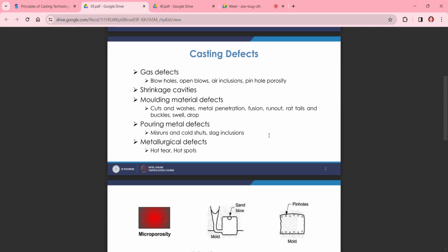Okay, so we are going to join those two halves with the help of some clamps. If the clamping is not proper, what will happen when we put the molten metal inside that mold? That will exert some pressure on the mold, and due to improper clamping, the material is going to flow out from that joint position. That will create the run out defect.